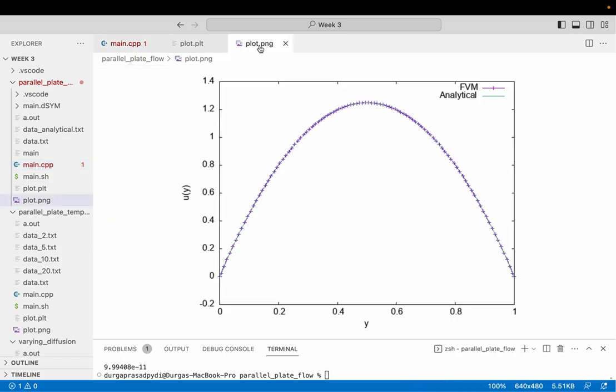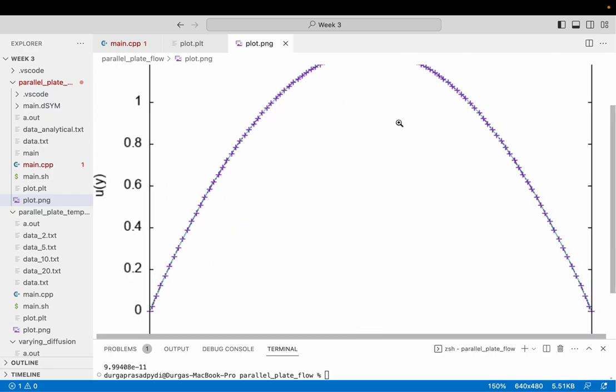I think the point I want to make here is, if you are using an iterative method, you need to be careful with your tolerance and your meshes. Both have to be chosen appropriately. Only then do your results make physical sense. Before talking about your accuracy and convergence, you need to ensure that both are taken care of appropriately.